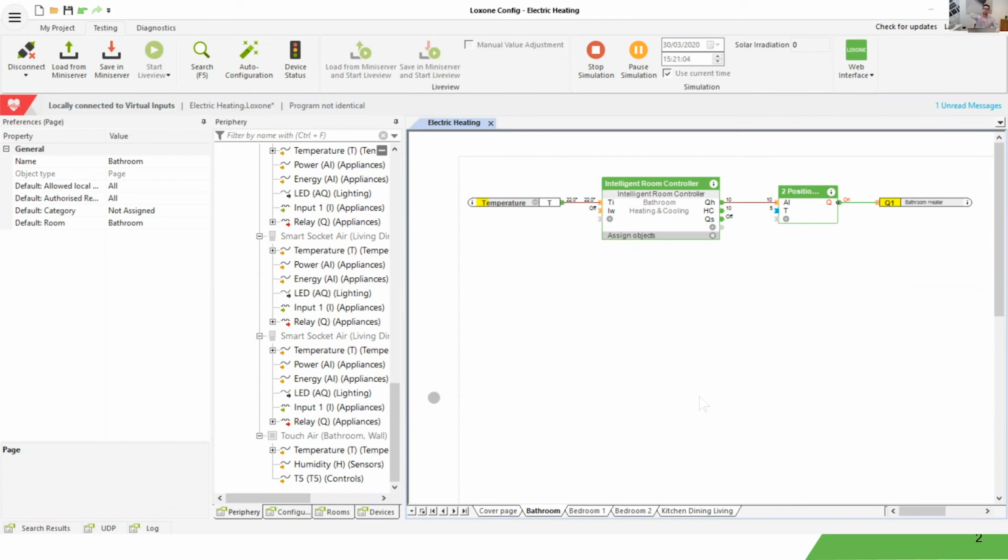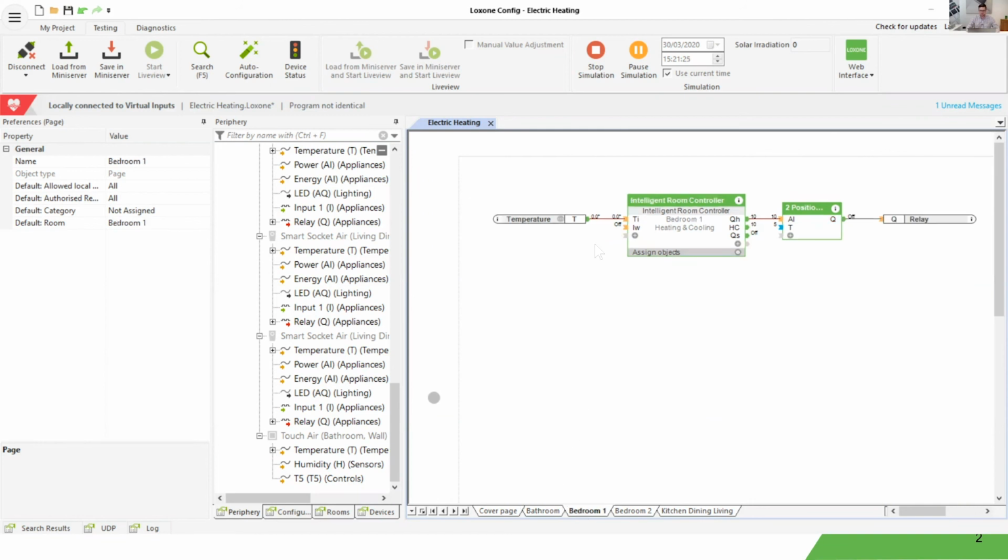And what it will do is it will learn over time how to adjust the slope to make sure that it's leveling it out. And so what you'll actually see, if you start whacking those temperatures up and down in simulation, is it will take a gradual effect. And there'll also be a scanning time as well. So there'll be something like a 60-second scan time in there. But if I do that for the other rooms as well, if I make this one, let's say 22.3,